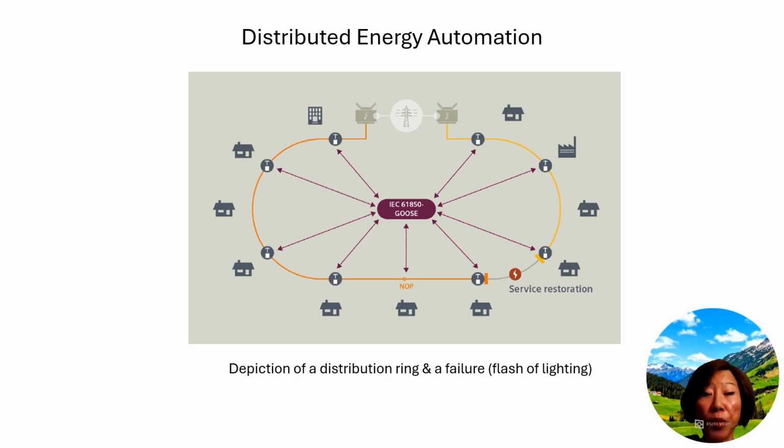These messages are sent periodically during steady-state operations, with intervals changing in fault situations. Each controller sends these messages to several or all other controllers on the same feeder, and they are not acknowledged.